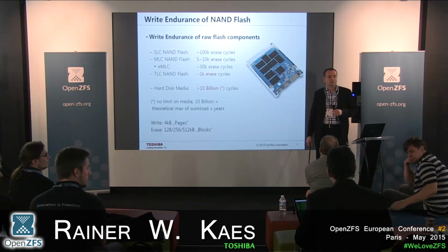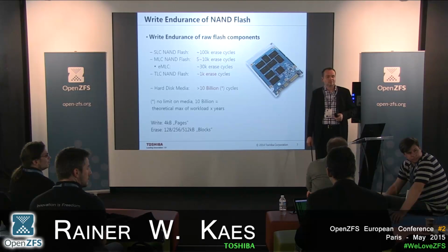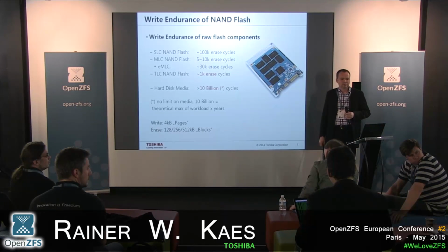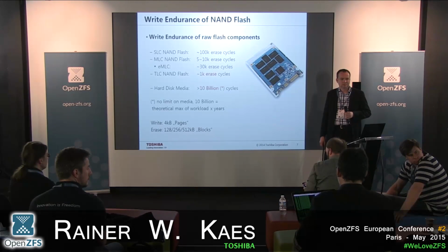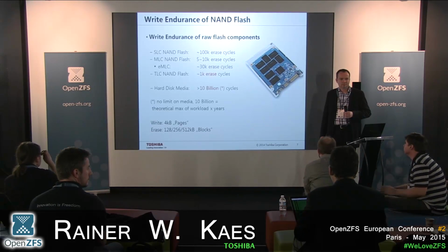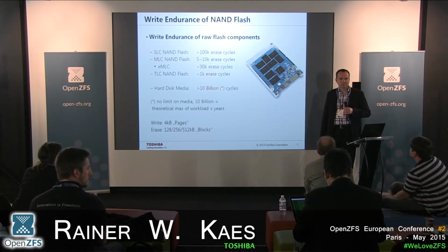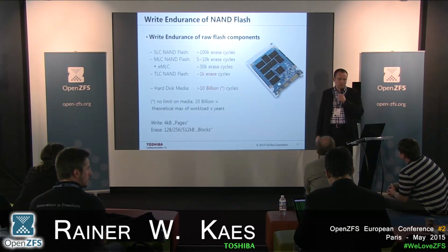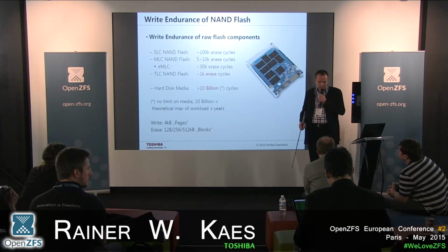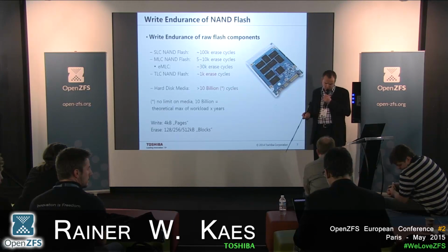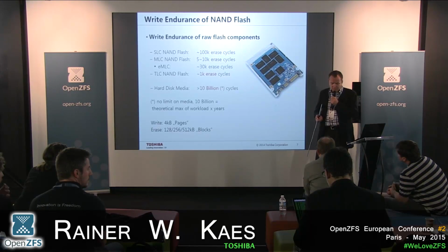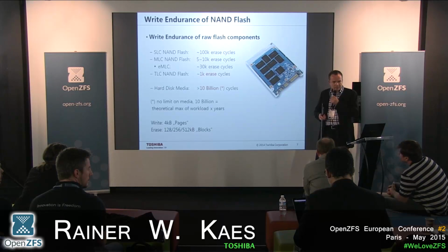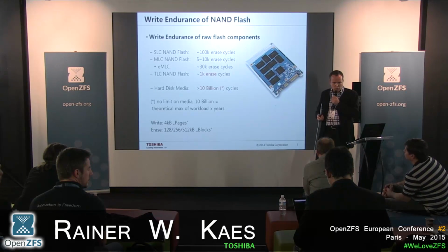You talked about the 3-month power off time. Does this mean that if you keep it powered on, the controller is continually going through and perhaps refreshing cells that are leaking, so that they last longer than 3 months if it's powered on? Yes. In an SSD, the data content is constantly shuffled around. We will see this later. So if you keep an SSD on power, it shuffles around the data in less than 3 months, so that you won't have an issue.